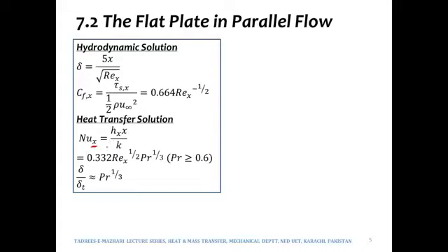And we had seen how we ended up getting hL over k in the previous chapter's material, where we had divided the heat transferred via convection, Q equal to hA delta T, by the heat transfer via conduction, kA delta T over delta x, and we ended up getting hL over k as the expression of Nusselt number. So this expression of Nusselt number, when solved, would give us this expression, 0.332 Reynolds raised to the power half, Prandtl raised to the power 1/3.